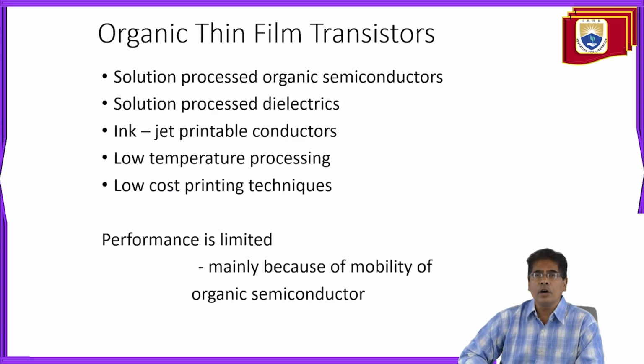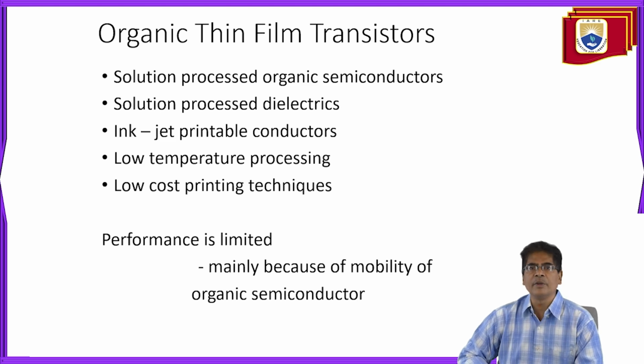In organic thin film transistors, we have solution processed organic semiconductors, solution processed dielectrics, inkjet printable conductors, low temperature processing, and low cost printing techniques. Performance is limited mainly because of the mobility of the organic semiconductors.